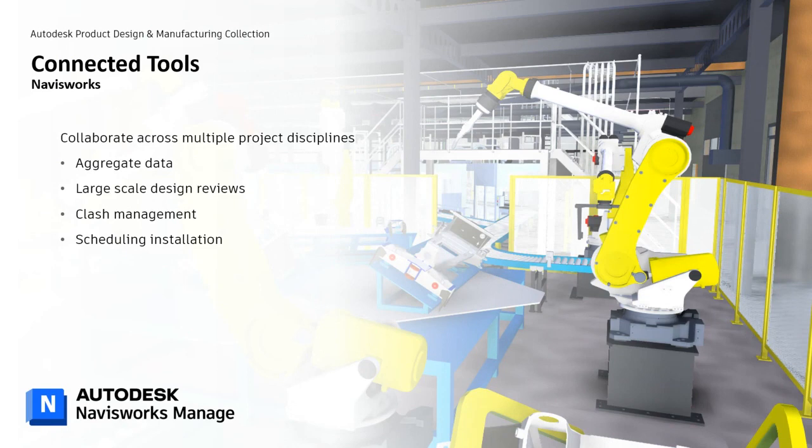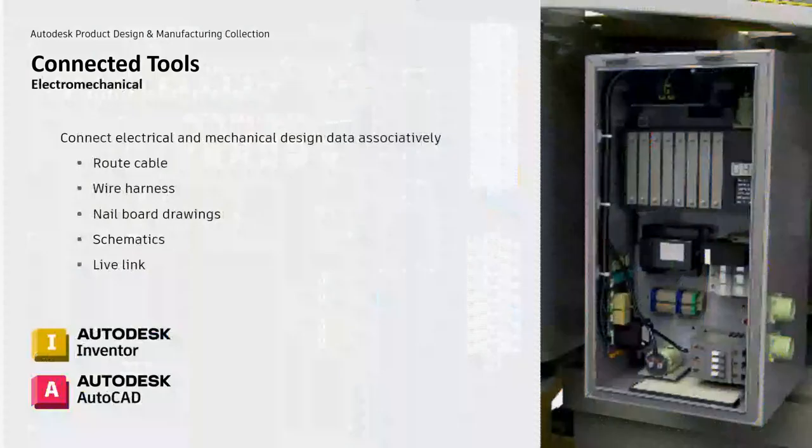This application is not only built for design review and walkthroughs, but it can also be used for clash management of models imported from other CAD systems, in addition to non-CAD data such as point clouds. So with timelining in Navisworks, equipment information can be synced to your project management software. This will help assist the installation process of your designs. So again, all of this can be accomplished while the data remains associative to the model data.